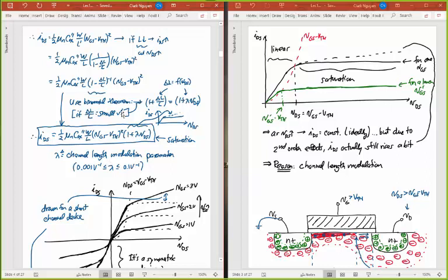But it's important to know the physics, especially if you're doing future design, designing a new type of circuit, which some of you may be doing here. When you're doing that, usually those who know the physics are able to get the best designs. If it's one company versus another company, of course you want the best design versus your competitor. And so this is the equation that dictates that current. It's really what voltages you're applying, the VGS voltage, the VDS voltage, and how when applying those voltages, you get a certain amount of current out of this. You'll see that later on when we talk about circuits, that will be very important.